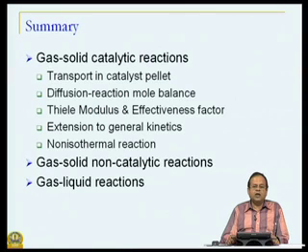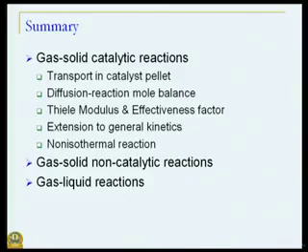Now, if you look at gas liquid reaction, even when the reaction is taking place, we can still look at the rate of absorption. Our observed rate is nothing but the rate at which gas is disappearing from the gas phase, the gaseous reactant. But now we compare this with what would have been the rate of this disappearance if the reaction was not there, and this rating parameter we call the enhancement factor.